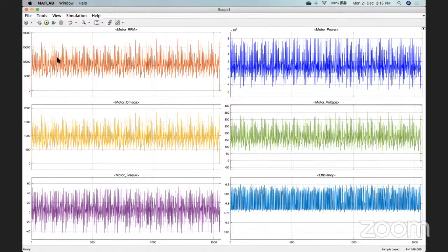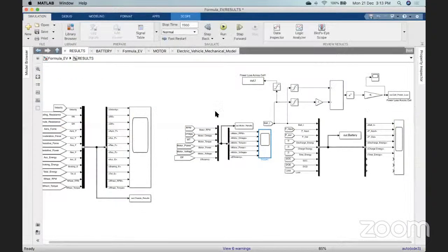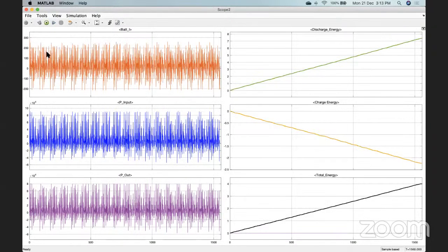So you can also develop different types of graphs from the data which you are getting from these powertrain simulations. Here I just plotted omega versus time. So what you can do is also plot omega versus torque, or omega versus power and all the stuff, and you can analyze where exactly this operating point is going and all these things. It will be fun to understand the parameters and developing your vehicle.